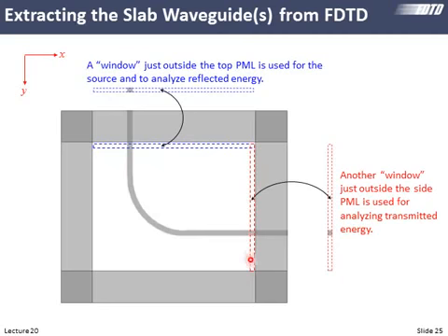We'll do another thing. We will also analyze the cross-section on the exit side. We have to do another analysis because whatever comes through here probably won't look like our pure fundamental mode anymore. And what we want to do is use the modes we calculate here to weigh our simulated field against the modes to figure out how much power is in each of the modes. And then the waves would hit the PML and get absorbed. So a real simple example of how we could model a waveguide circuit.